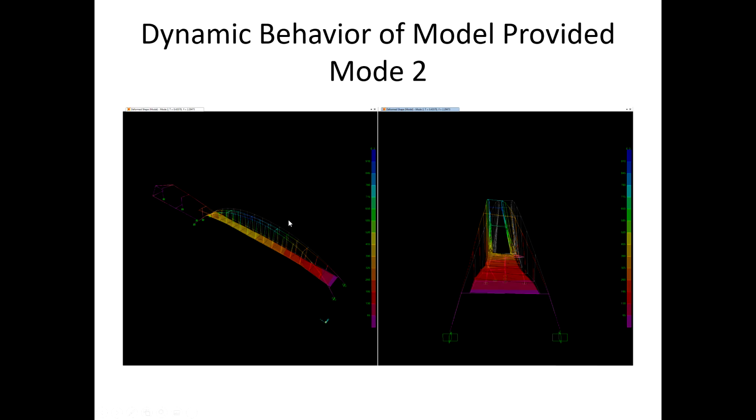The second mode is side-to-side swaying, you can see that better here. And so if we want to capture this mode, we're going to need some sensors up a little higher on the bridge. You'll see that in the plan, because there isn't a lot of up and down motion in this mode.